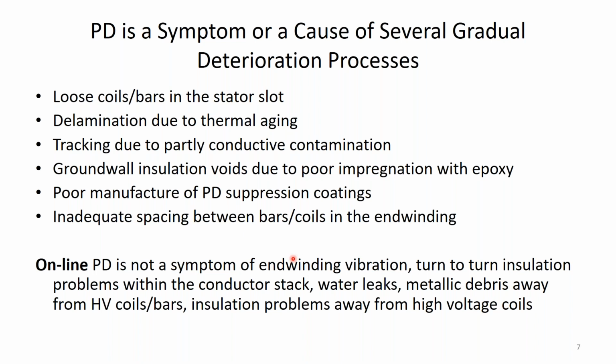And unfortunately, winding vibration is a huge problem right now for a lot of turbo generators, air-cooled turbo generators made since about 2000 to about 2014 by virtually most of the world's manufacturers. These would be air-cooled machines less than a few hundred megawatts. Okay, there's a big winding vibration issue right now. One insurance company says 50% of all the money or claims they paid out has gone to winding vibration of the stator windings. We can't detect that with PD, so obviously that's why we are also into winding vibration sensing.